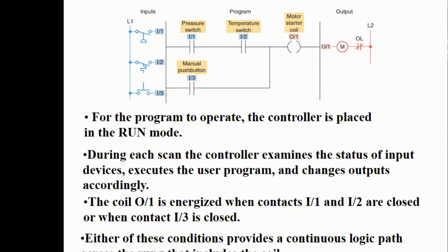There's a scanning cycle that is taking place. The controller is reading what's going on in the outside world, how that information compares to the actual instructions, and what needs to happen to control the devices you're trying to control.